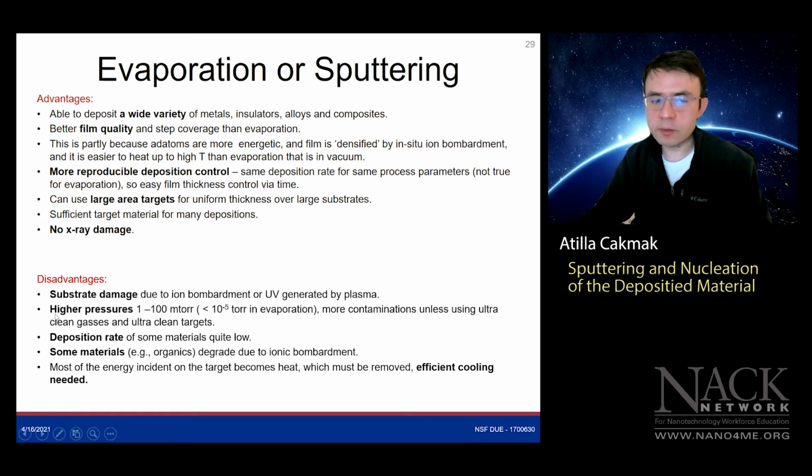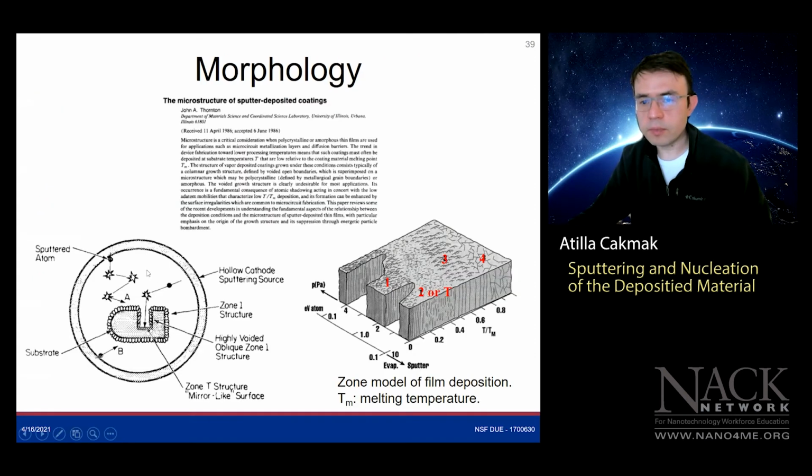The disadvantage is we're using higher pressure, so it might be dirtier. And the deposition rates of some materials might be a little bit lower. And some materials may not be doable with sputtering because you're doing ion attack, right? Ionic attack. That's going to be too heavy for those materials and it will not work. So yes, like I was saying, you will be able to find a lot of these details that I jumped over in the supplementary, for the sake of showing you more simulation results.